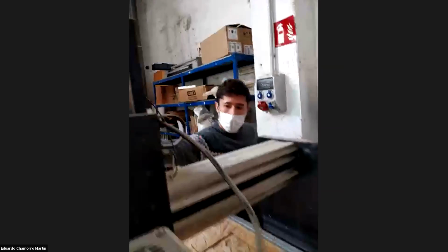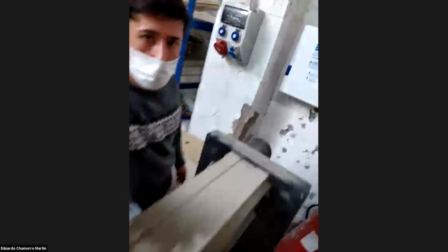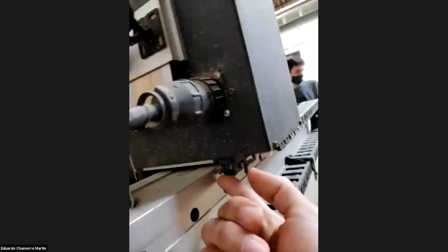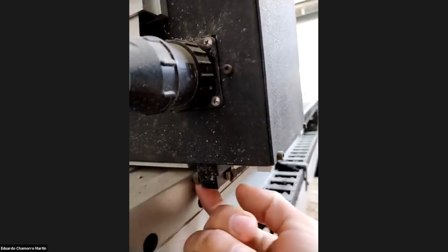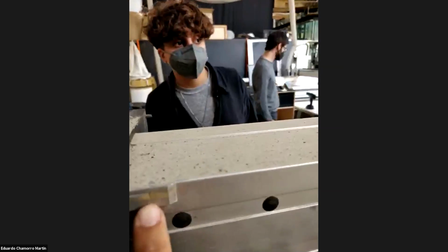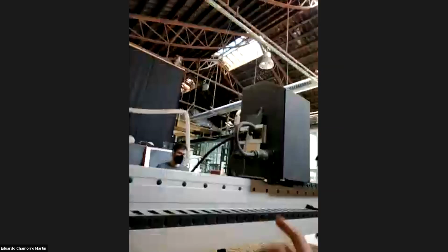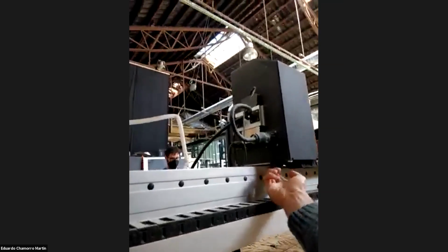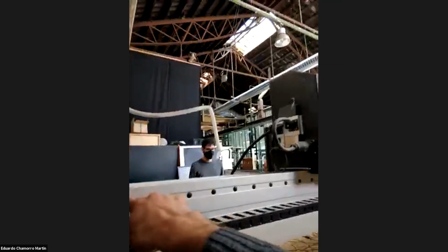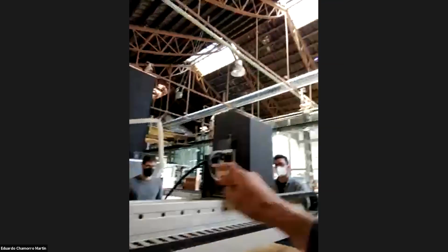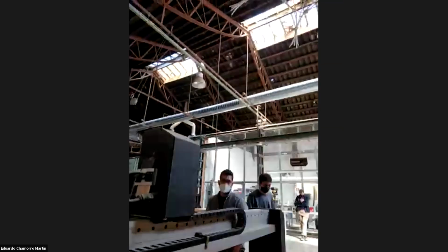So this axis here has this little end stop in there that when it gets to the end of the rail, it gets pushed by this element in here. If you come to this side, you'll see it. So you see that there's just a normal switch that pushes, and you get there, and you know that you are at the end of this machine. And you have the same on the other side, so that you don't hit. And you see that it's asymmetric on the other side.